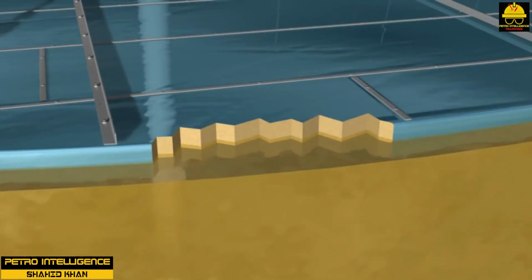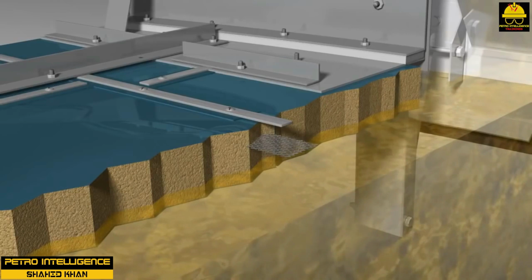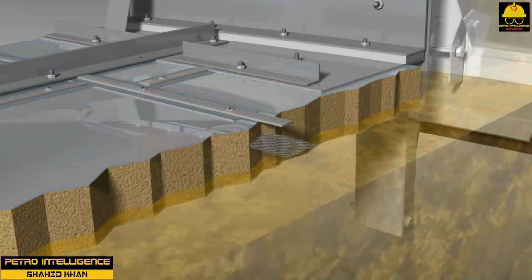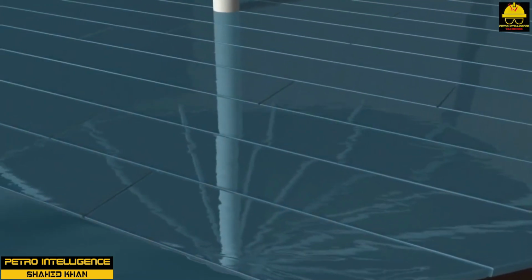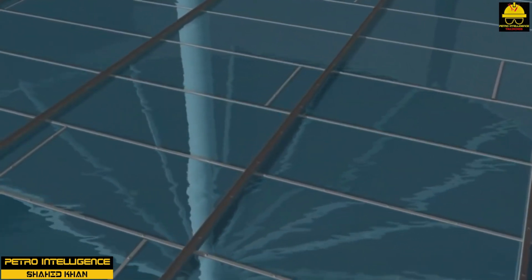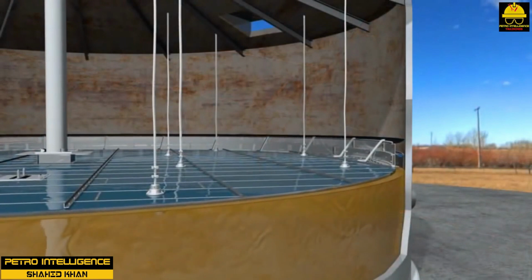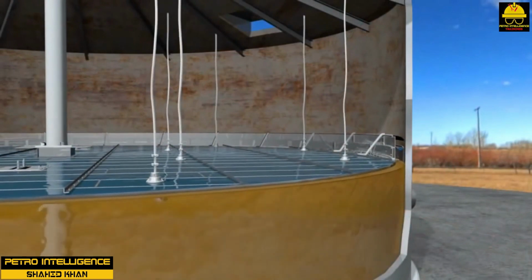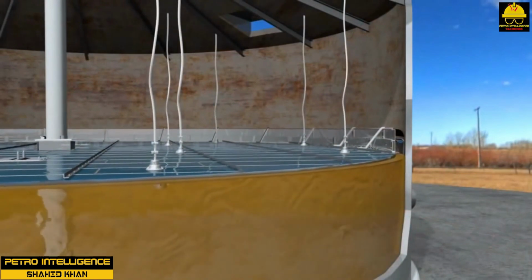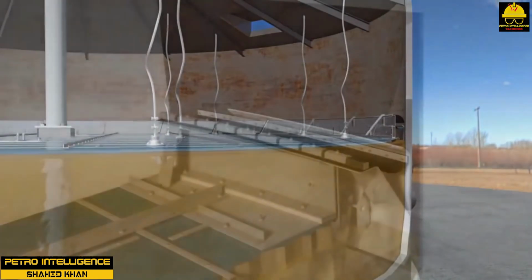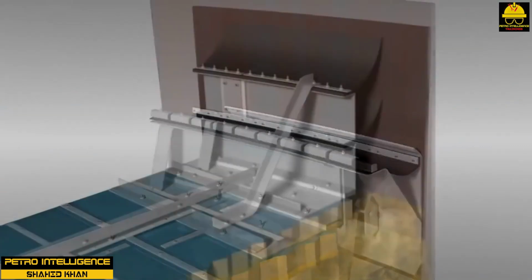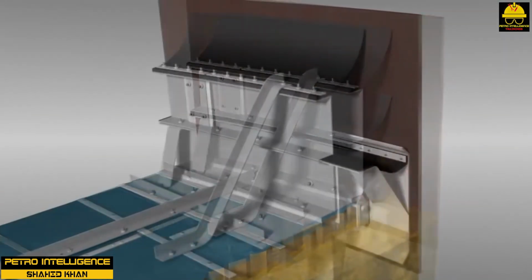The pontoon type of floating roof has an annular, ring-shaped pontoon around the outer edge and a deck of single thickness at the center. The annular pontoon at the outer edge provides airspace insulation for a large area of the liquid surface, which is helpful in retarding boiling of the product. The pontoon roof is quite stable because rainfall will run to the center and cannot make an uneven load near the edge of the roof. Likewise, a leak in the center section of the roof will not sink the roof or make it unstable.